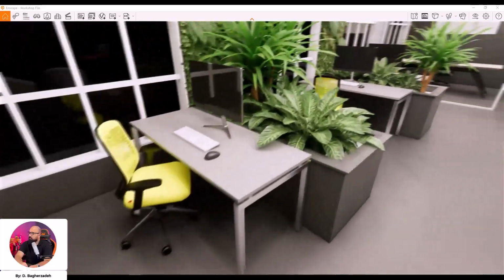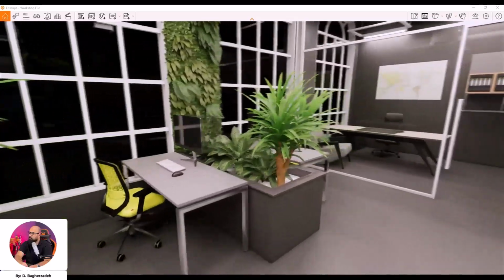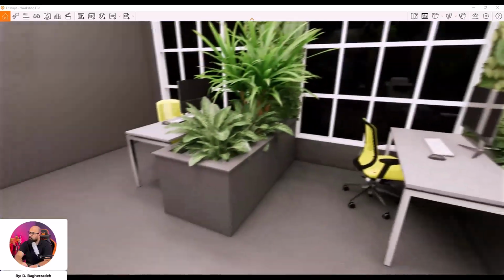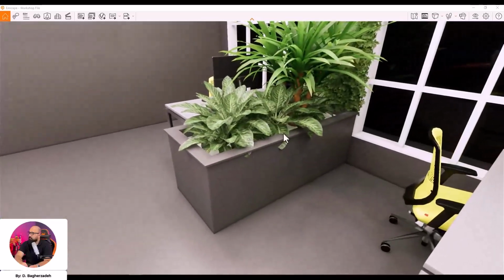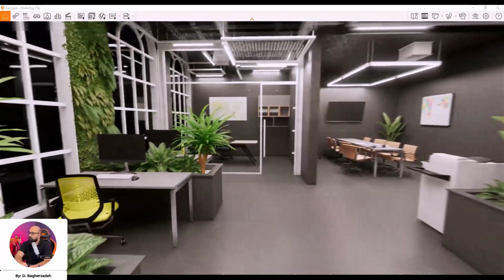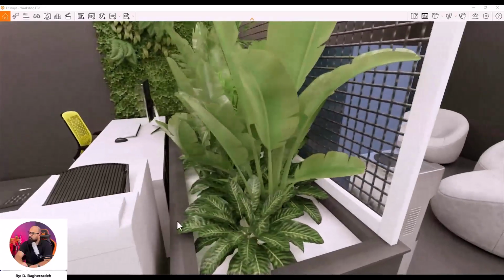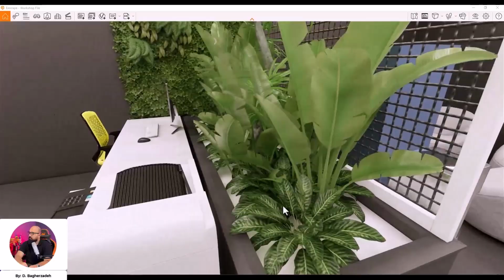Take a look at the plants. We have different types, some of them are rotated. We somehow try to create some sort of a diversity here. And by the way, sometimes we might face a colliding situation like this. To solve such problems, you can, for example, rotate your families a little bit, or you can choose your rendering angle in a way that none of these visual mistakes would be displayed.